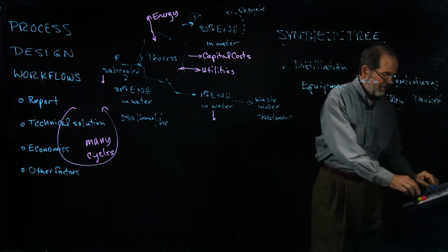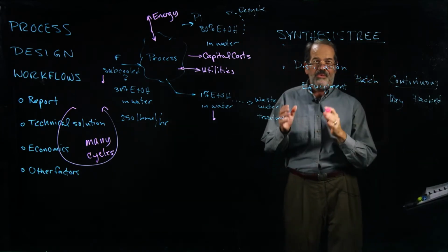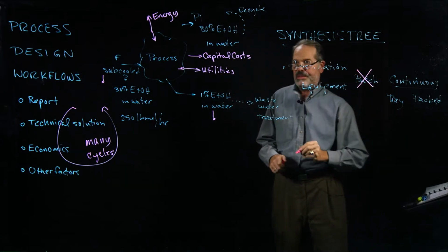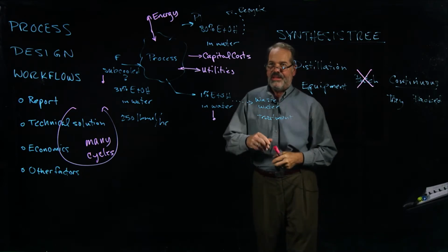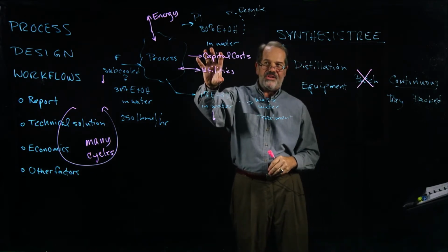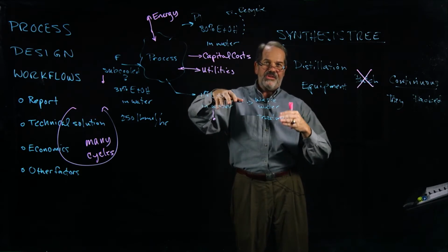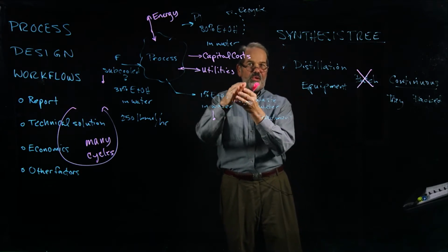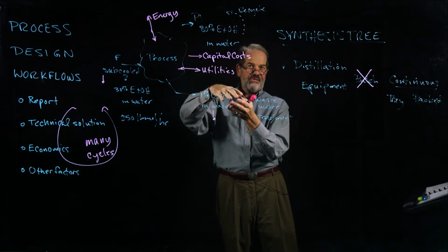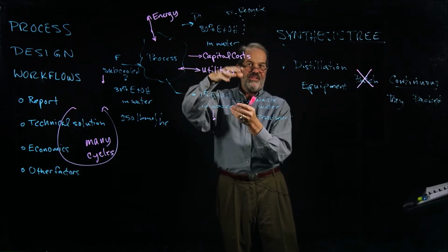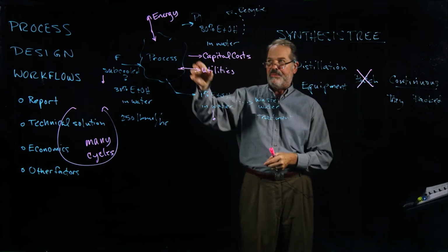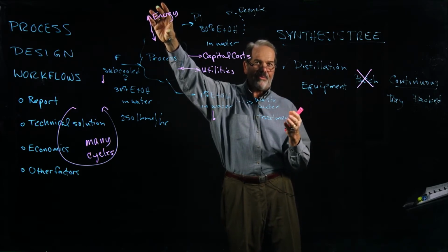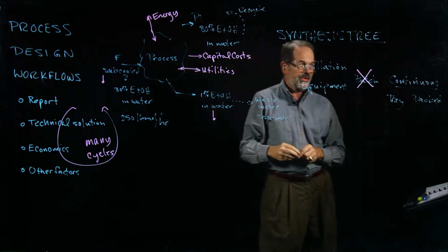In general, if we're not doing specialty chemicals, or we don't have any unique specifications, we probably will not do a batch separation because, since we're starting and stopping things, it tends to have startup and shutdown problems. Utilities are discontinuous, so you have to size the utilities for more than an average rate of delivery. You have to size it for when you are working, which will be at a faster rate than if you did a continuous process. The energy requirements during the time you are running the batch process will be higher than they would be for a continuous process as well.